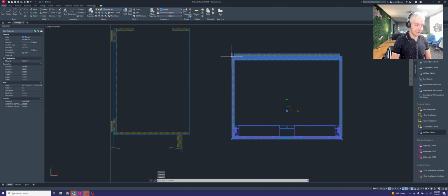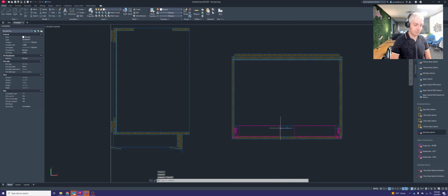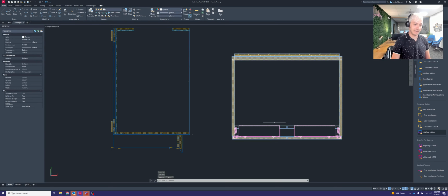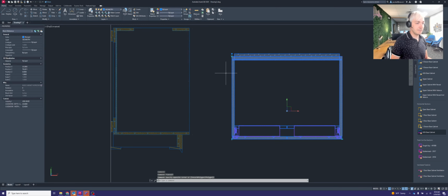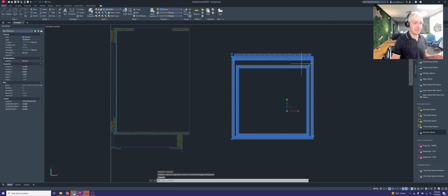So if you need an ADA cabinet, this actually shows that metal bracket, the easy kick we talked about in the cabinet hardware video. If you need like a drawer cabinet, this allows you to show the drawer. It also limits you to having those 2-inch increments for the drawer slide. So you can't actually draw a drawer that's outside of that 2-inch increment.